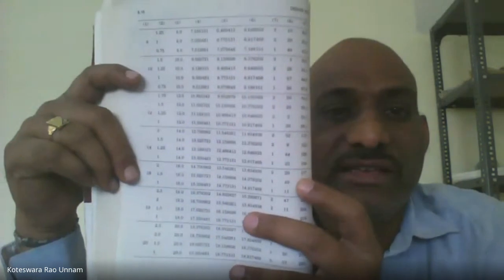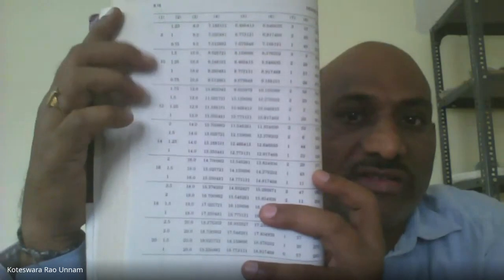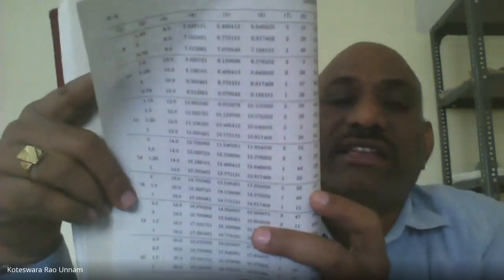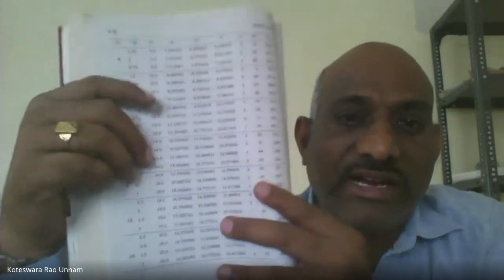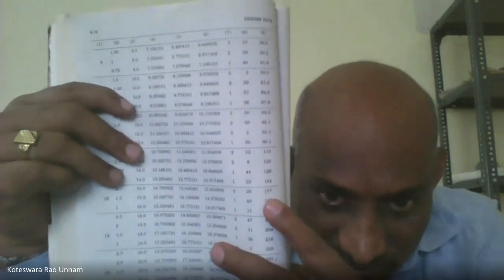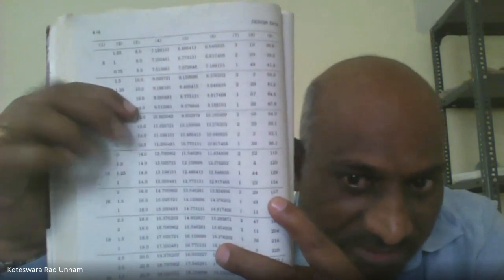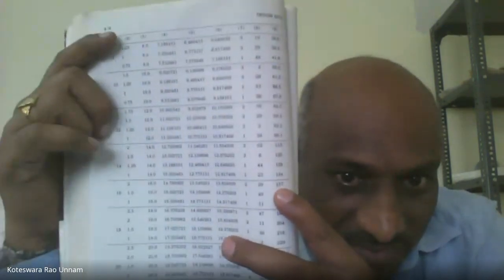So the answer for the question is, you need to select M16 as the nominal diameter. Whatever column you have here, this value M16 is nothing but your nominal diameter. Like that, you need to choose the value from the data book. I think now you can understand that. Is it visible to you here, 157? What I placed here, I am pointing to 157. Is it visible to you? Maybe if you have a data book, you can go through that if it is not visible. Like this, you can select the data, you can choose the data from the data book, whatever you require.